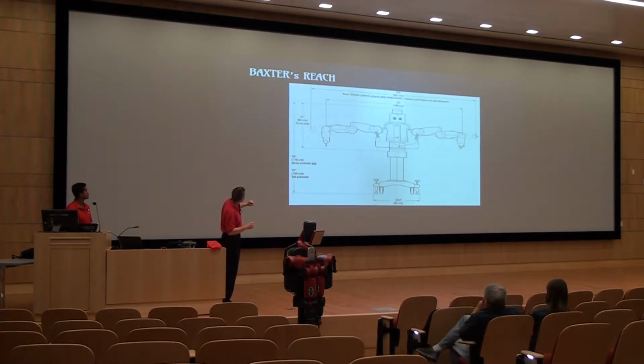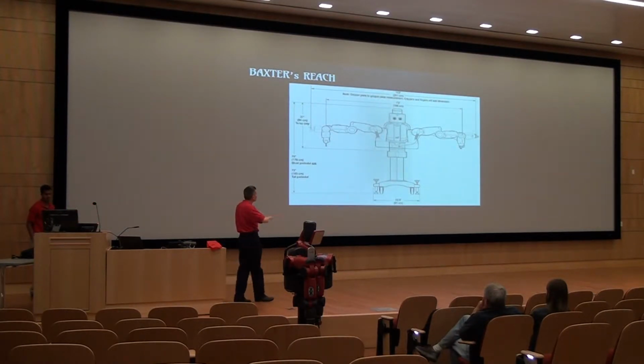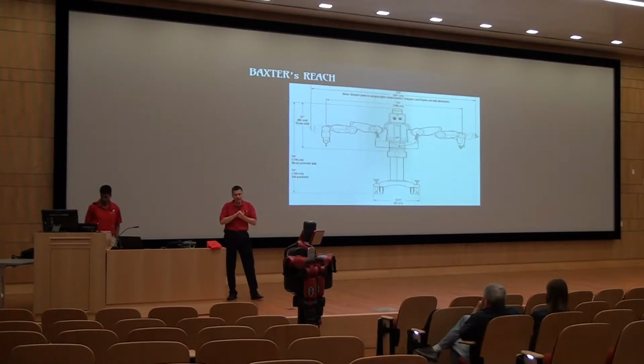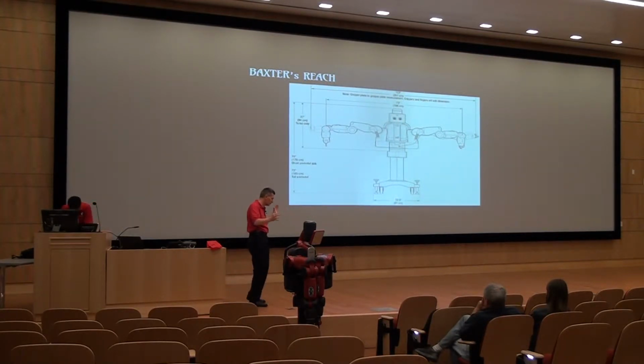This doesn't look so clear, but it has a considerable wingspan, given that it is a dual-arm robot, over 2.5 meters in its span here. So it has quite a work envelope that it can work in. And like a typical industrial arm, it basically follows a kidney-shaped sphere in its work envelope.